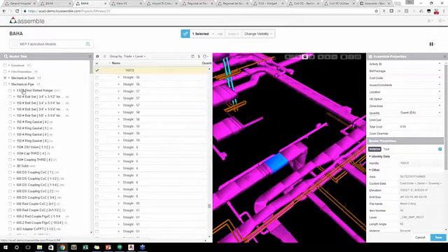So you'll notice a couple of quick points, and we'll go from there into questions. Within AutoCAD, we don't have information structured like we have in Revit. Revit has a very structured set of data regarding categories, families, types, etc. Within AutoCAD, we have to create some of that information based on the data that's there. So we're actually creating a category here so we can organize it the same way that we do with Revit. We're actually creating a type name the same way and organizing the same way we do with Revit.